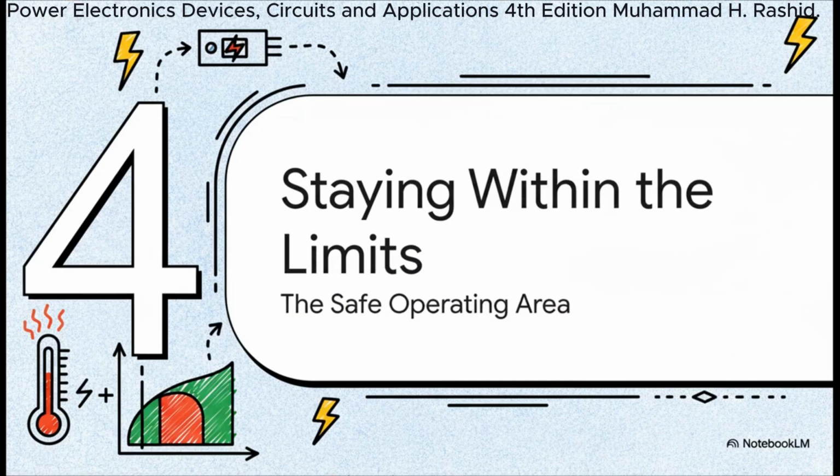Which brings us to probably the most fundamental rule of all. Section 4, staying within the limits. Every component you ever use will have a datasheet. Think of it as the component's Bible. It tells you exactly what it can and cannot do. Your job as an engineer is to know those limits inside and out and design your circuit so it never pushes the component past its breaking point.